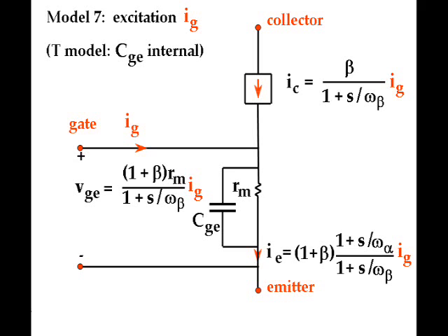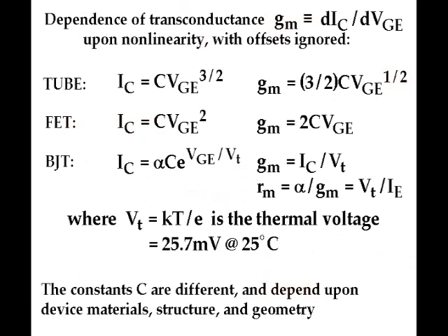The emphasis here is on the commonality of the basic functions and the equivalent circuit models of all charge control devices, and only basic effects have been included. However, as already mentioned, the nonlinearities can be considerably different, which leads to significantly different dependencies of the small signal equivalent circuit elements upon operating point.